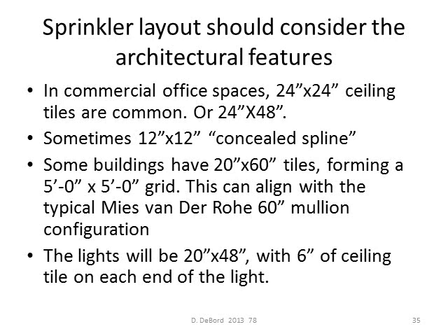Sometimes we have 12 by 12 ceiling tiles, which would normally be a concealed spline. With the 24 by 24 ceiling tiles, you'll see a strip between each tile that actually supports the tiles. They're lay-in tiles, and they sit in that framework. You can push them up out of there. A concealed spline, they interlock together, and you do not see what's holding them together.